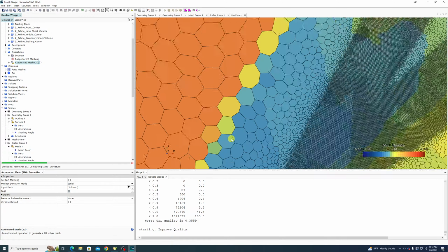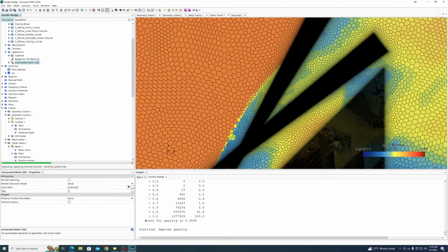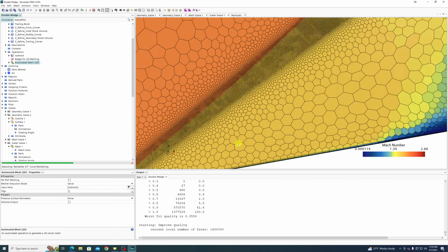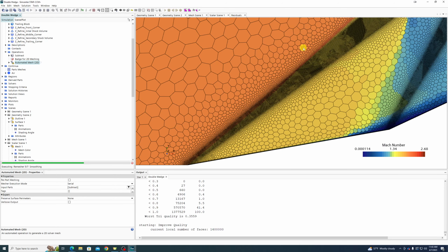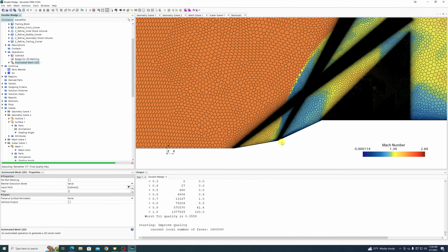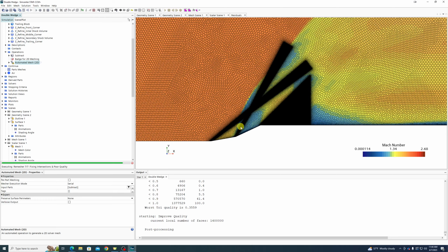Yeah, but see, in this space, we're going from... Well, that really looks like kind of actually... Well, actually, this agrees pretty much exactly with what we'd expect, because I was expecting this to be a weak oblique shock, an attached weak oblique shock, which drops the Mach number to about 1.5, from 2 to 1.5. And this is actually in the realm where this would be expected to be a strong shock.